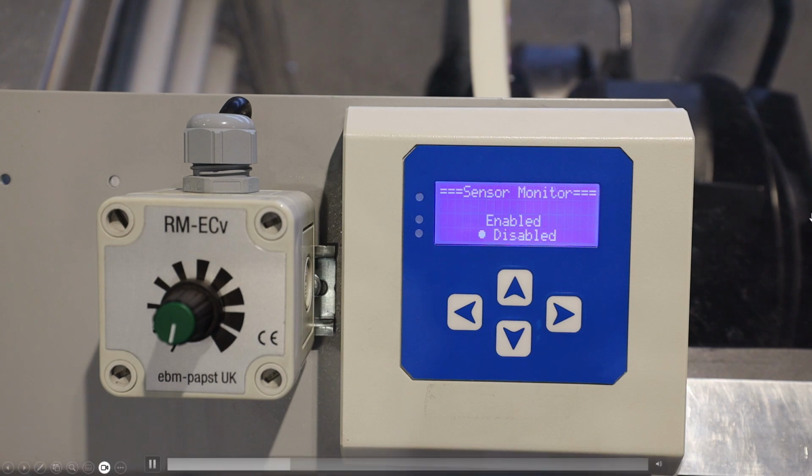Whether volume flow or pressure measurement is required. What the measurement range of the sensor is, and the fan inlet ring K factor if volume flow measurement is chosen. In this case, the source of the sensor will be set to fan analog input 1 and we will choose pressure differential, and the sensor we're using has a 0 to 2000 pascals range.